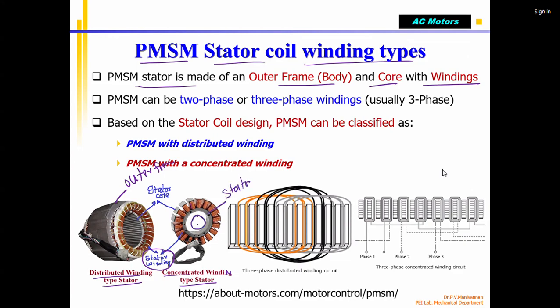Inside which only the rotor will be there. Inside which the north and south pole rotor is going to be there. This is the stator core on which there are projections like this one, on which coils are wound over the poles, correct? The whole thing forms the stator. So here the windings are concentrated on the projected pole-like structures. That's why it's called a concentrated winding stator.